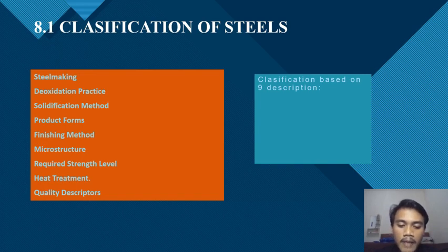The various types of mill steel products include sheet and coil of low carbon steel for applications ranging from cars to appliances, wire used in such products as bed springs, wire rope, nails, and wire fabric, structural shapes used in buildings and bridges, and bars for forging and machined parts such as gears and bearings. Finishing method: the surface of the steel product is influenced by its finishing method. In a rolled mill product, finishing is by either hot rolling or cold rolling.